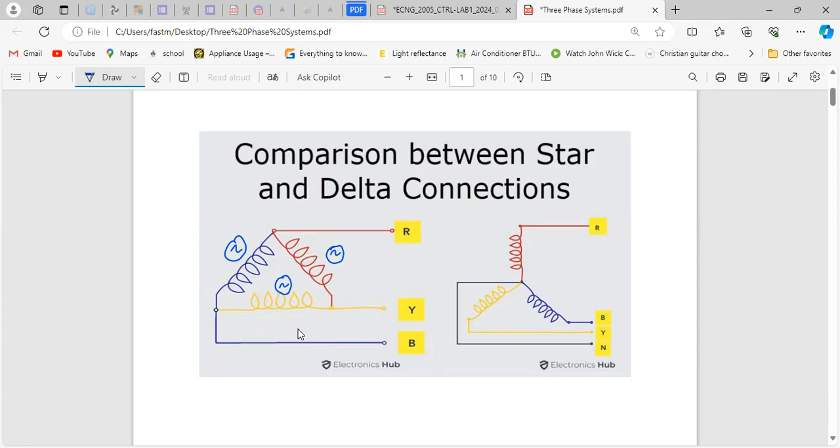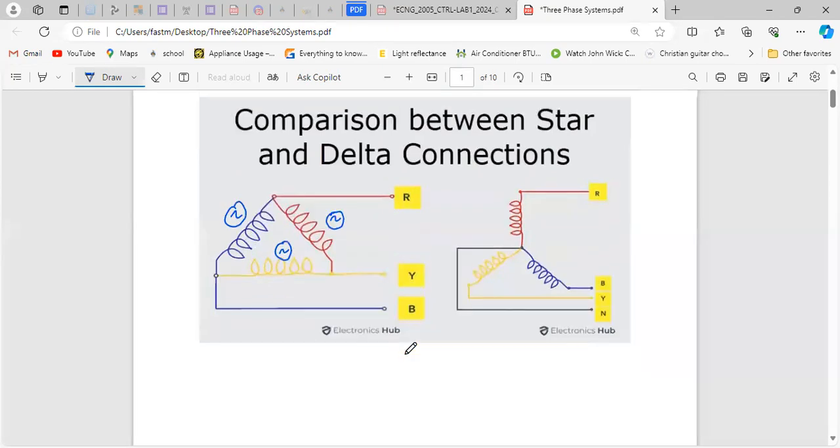They go into the red, yellow, and blue line voltages. So that is what these lines on top here are, and these are the transformers. That's how they get the three phase systems. Basically, there are three single phase transformers, and each transformer has a line. When you pull all three together, you get a three phase transformer, or a three phase supply, whatever you want to call it.